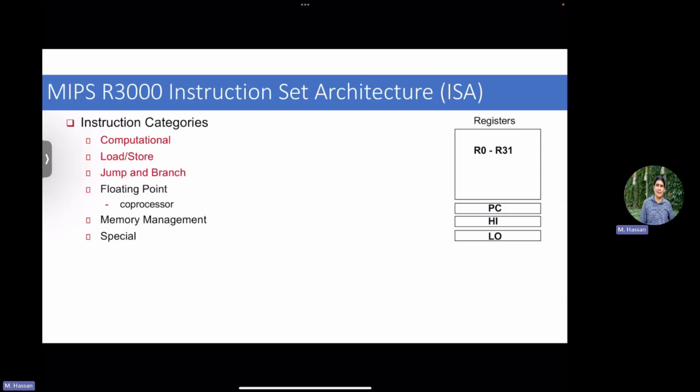So we're going to spend a couple of lectures going through the ISA. We said ISA is the contract between the hardware and software. So again, as an architect in the hardware, you are implementing the ISA, right? That's basically the document you open, look into instructions, and build your circuits based on it, right? Based on the series of bits of the opcodes, of the register operands, and what operations you need to support, what flags you need to support. So without understanding the ISA, you will not be able to build a computer, right? Like a computing machine, a processor circuit, data path and control path. Good. So this is why we're going to go through the ISA in some sort of detail.